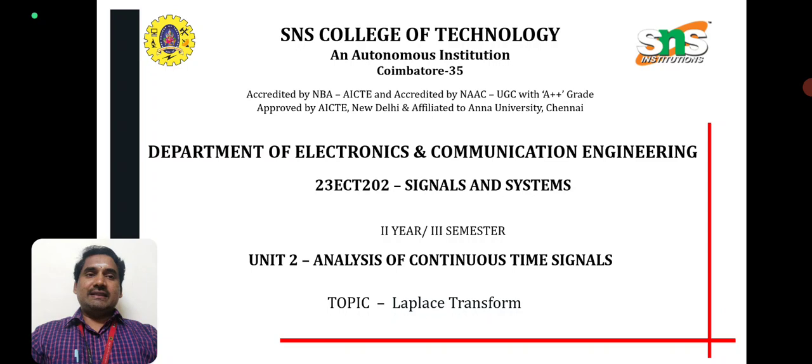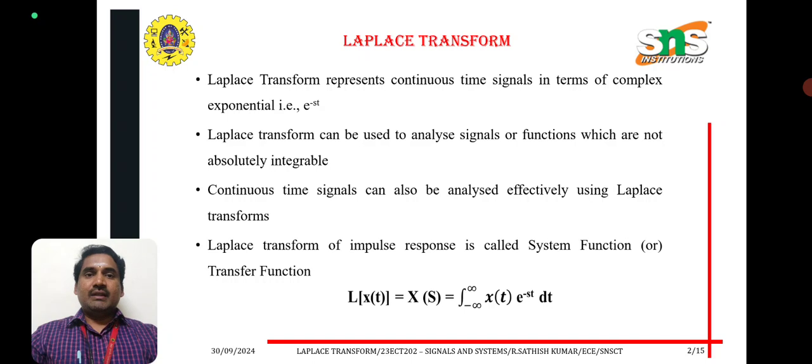Now let us see the video lecture series on Laplace Transform for analysis of continuous time signals. Laplace transform represents continuous time signal in terms of complex exponential, that is e power minus st. Laplace transform can be used to analyze signals or functions which are not absolutely integrable. Continuous time signals can also be analyzed effectively using Laplace transform. Laplace transform of impulse response is called system function or transfer function.